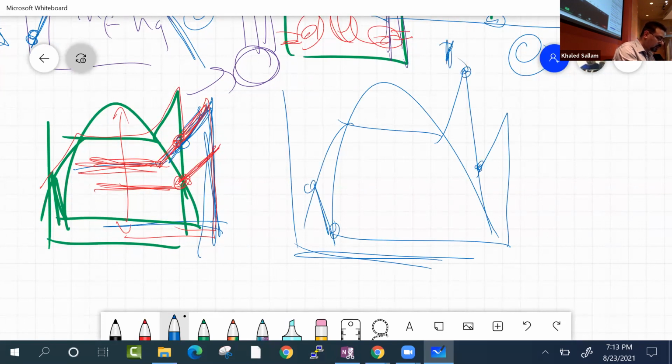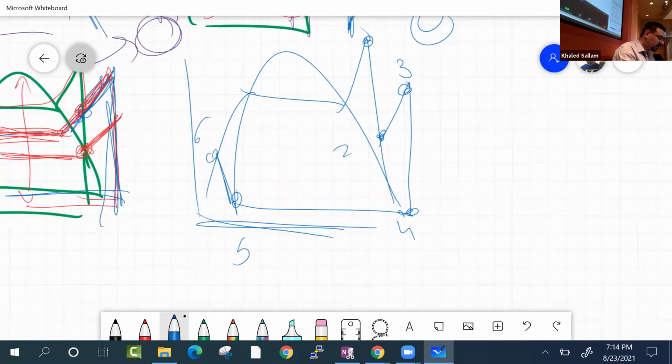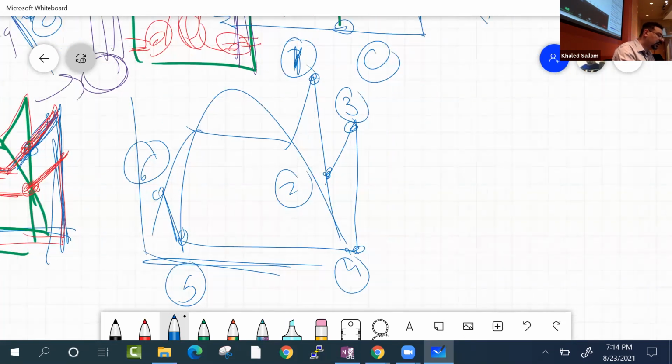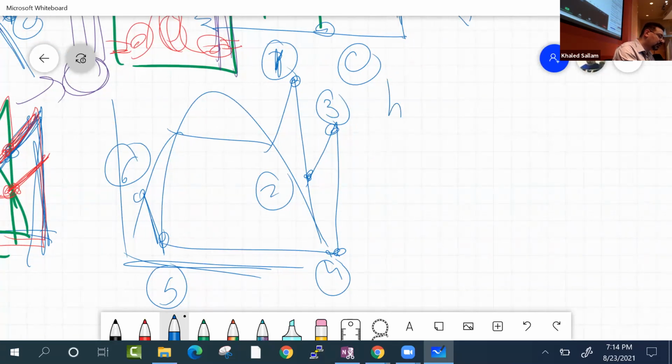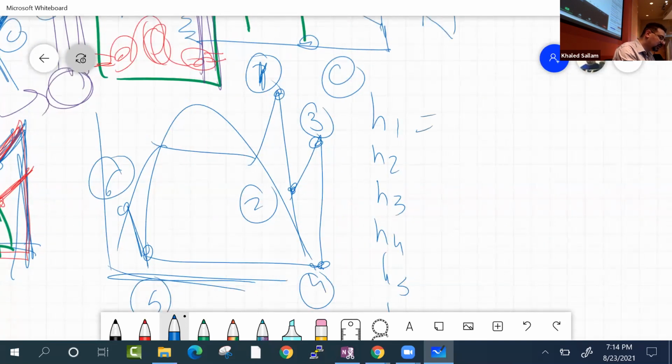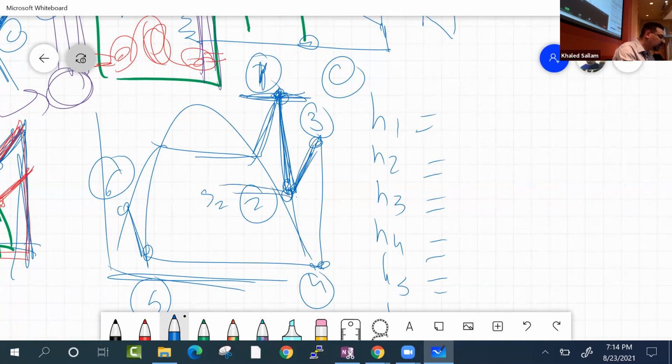So 1, 2, 3, 4, 5, 6. Just like any cycle, we start with H1, H2, H3, H4, H5, H6. You get all the H's. Ask yourself, can I calculate all those H's or not? H1, how can I get H1? I know the pressure, I know the temperature. H2, how can I get H2? That's the same as isentropic expansion. So I know the entropy, S2, and I know the pressure too. How do you know the pressure too? I said that I was trying to find it.